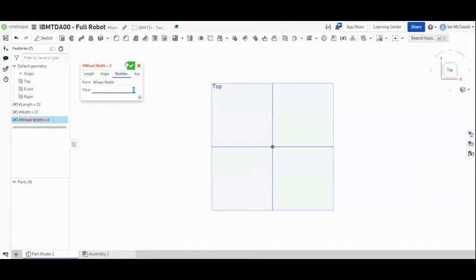what's going to happen is that when I try to save it, you'll see this has gone red. Red is a color that they use to indicate there's a problem. So if you do this, you can hold your mouse over it and it explains it, and it must be a letter followed by a string of letters or numbers. So I can't do it with the space. So that's a really important thing, watch for red. If there's red, then you know there's an issue, and solve the issue. So green check mark. So I've got my variable set.